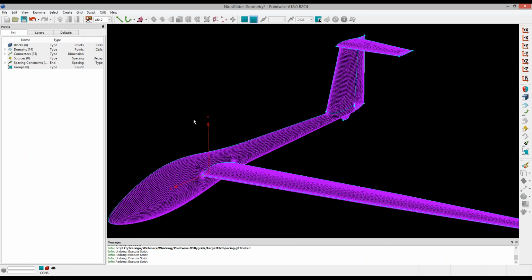The next step is examining the quality of that surface mesh. I'm going to hammer this hard because I think this is important to talk about. There's no reason to take a surface mesh that hasn't been examined and try to generate a volume mesh from it, okay? Because in the end, like I mentioned before, you're going to be advancing elements off of the surface. So if you haven't looked at the quality of the surface, or the quality isn't up to what you want it to be, right? It's violating some metric that you've specified. Go ahead and inexpensively make modifications to the surface rather than generate a volume mesh to identify those problems later and expensively have to fix them, okay? Because generating a volume mesh, granted, is an expensive process. It's much more expensive in terms of time than generating a surface mesh, okay?